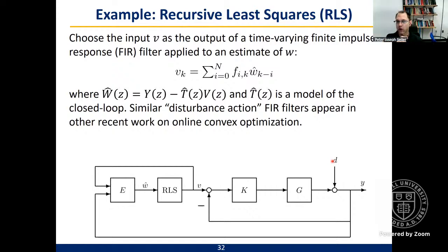There are all sorts of requirements, like the probability that this is going to fail is 1 out of every billion hours, or 10 to the minus 9. That drives you to things like three separate computers implemented to do the flight controls. Each computing box has three separate processors, so that no chip flaw in any one of the chip lines is going to bring the airplane down. So you get lots of redundancy built in, which I haven't talked about here.